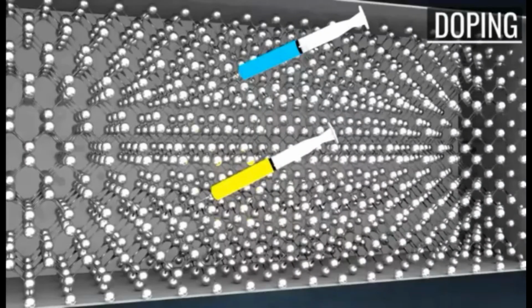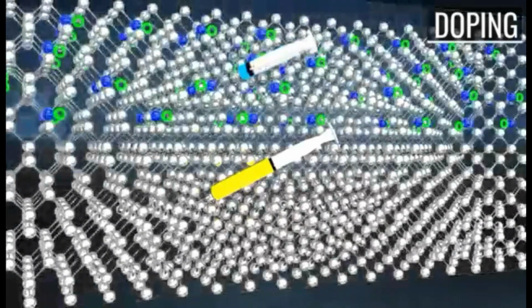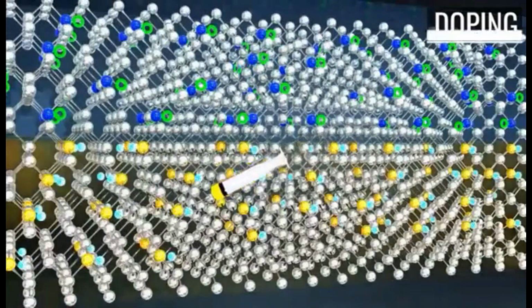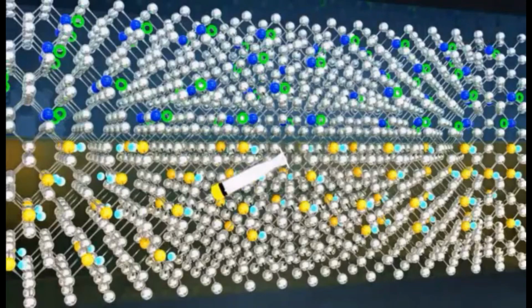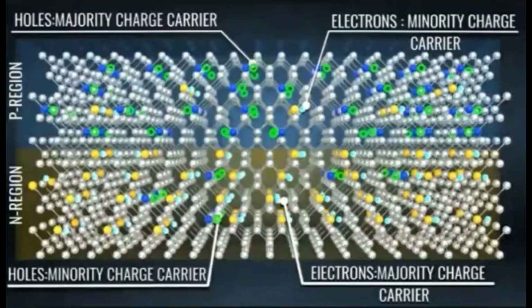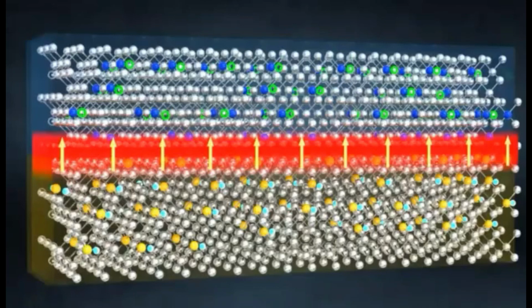A p-n junction is the simplest form of semiconductor diode that depends on the interaction of n-type and p-type semiconductors. An n-type semiconductor has plenty of free electrons and a few holes. On the other hand, a p-type semiconductor has plenty of holes and few free electrons. The free electrons of the n-type will interact with the holes of the p-type, then it will increase the number of electrons and holes at their center, and we call that the depletion region.